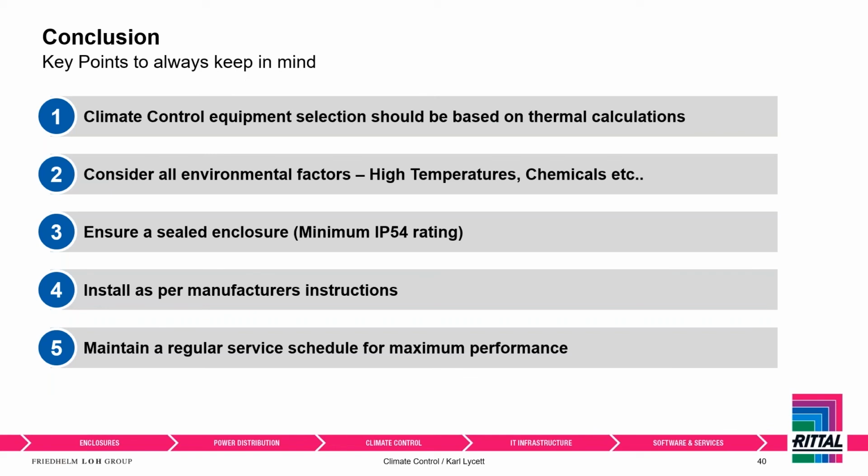Okay, so in conclusion, number one, climate control equipment, select it based on thermal calculations. So use that Therm software to make an educated calculation on the climate control equipment you require. Number two, consider your environmental factors. Have a walk around your site, have a think. Do I see high temperatures? Does Big Dave take his sweater off every time it gets warm, and those sorts of things? Are there chemicals in the air, is it dirty?